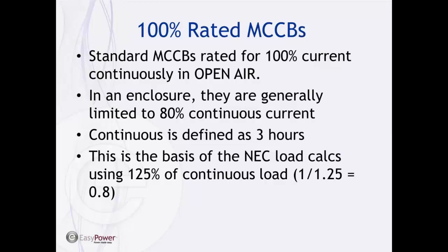In an enclosure, they must carry 80% of their continuous current rating at the 40 degrees C ambient. So if I have a 100 amp breaker in an enclosure, it can carry 80 amps continuously. Continuous is defined as 3 hours or more.